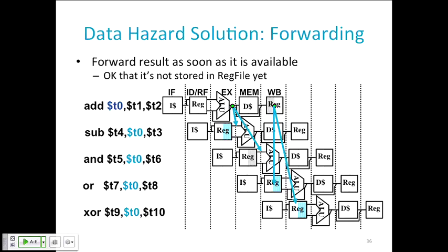Well, the general case is actually pretty straightforward. For any instruction, you decode it and find out, does this instruction write a register, right? If it writes a register, where does it generate the value that it's going to write to the register? So all the ALU instructions all produce the value here. They do write a register and it's ready here.